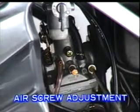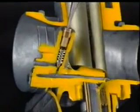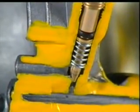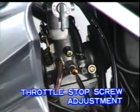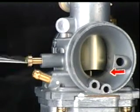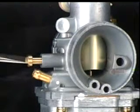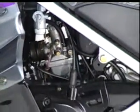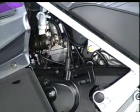Because of this, turning the air screw changes the amount of air taken into the pilot system, and this changes the fuel-air ratio, which in turn changes the idling speed. Turning the throttle stop screw, on the other hand, causes the throttle valve to move up and down, and this changes the amount of fuel-air mixture sent to the engine, thus changing the engine speed. Therefore, both of these screws are turned to adjust the idling speed so that the right mixture of air and fuel can be obtained.